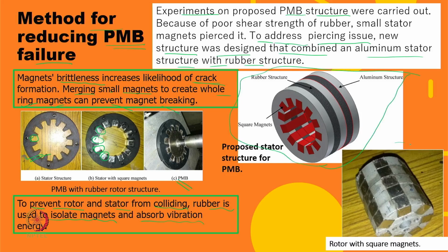So, now you can see, to generate the same magnetic field on a stator and permanent magnet, the demagnetization should not happen. Another one, they have sufficient room to absorb the vibration or the shock from the outside surface. So, there is some sort of coasting up and coasting down behavior that can be sustained. As I mentioned, in steady state performance, permanent magnet bearings work well. So, if you want to operate this 24/7, a permanent bearing will be a good solution.